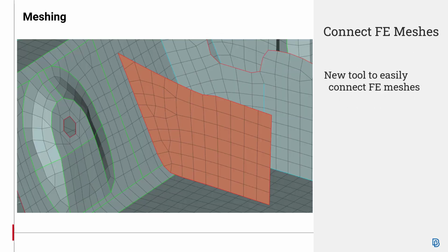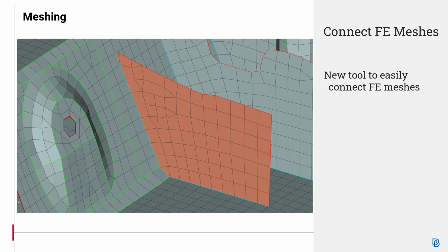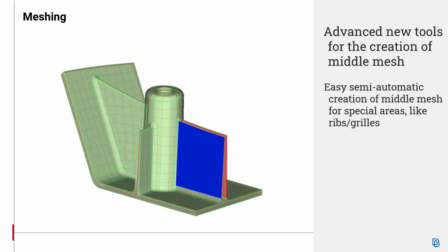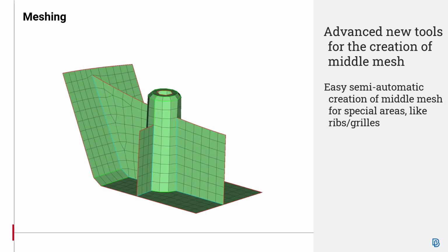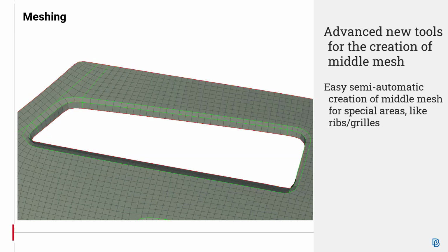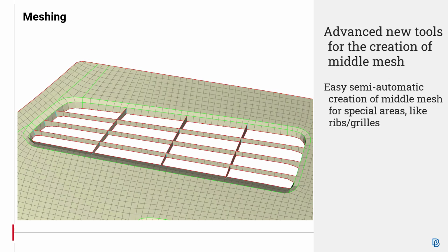Moreover, a new tool to easily connect element edges to a given shell mesh is now available, while also we added new advanced tools for semi-automatic creation of middle mesh in special areas like grills and ribs.